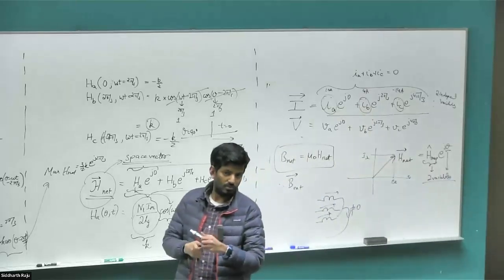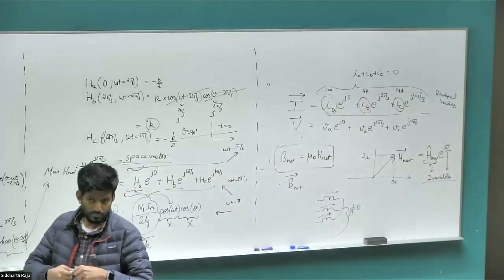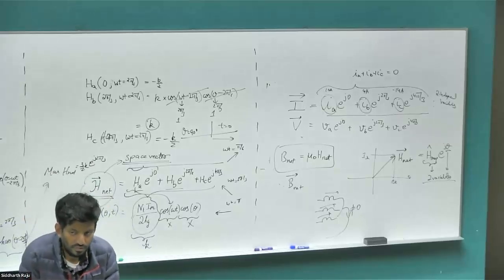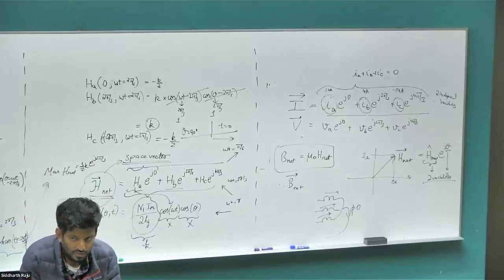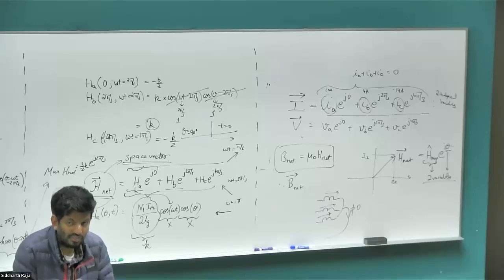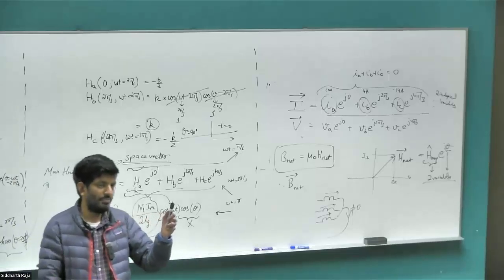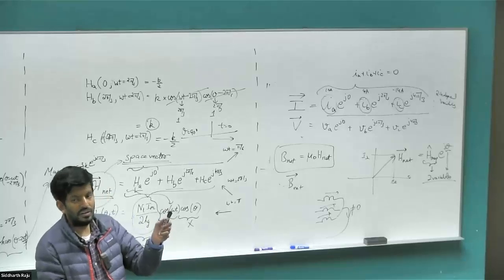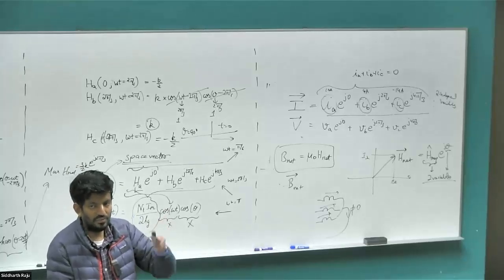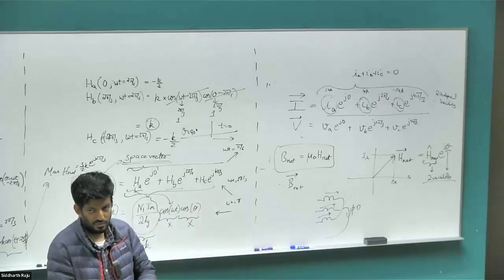Any questions? Yeah, sure. Just to clarify, H net, the space vector, is a function of time and theta, right? It's a function of time. Just time? Yeah, the theta will come out of the time. Okay, so that could be any angle where you're measuring H net. Yeah, H net is basically pointing to the H field where it's maximum at any given time. Right, so given a time, the peak will be at one particular point. Right, it's not a sweep of all the values. Okay, got it. Thank you.